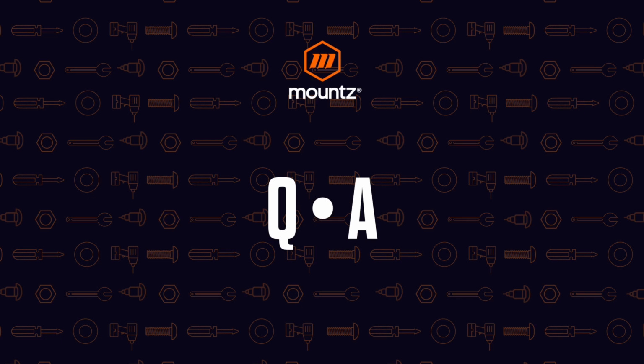Thanks, Dave. Yeah, we have a couple questions here. The first one is, what is the maximum torque in foot-pounds for Mountz DC electric controlled tools? So with the DC tools, we have a max of 50 Newton meters. So we're going to be in that ballpark around 37 foot-pounds or so for those DC controlled tools.